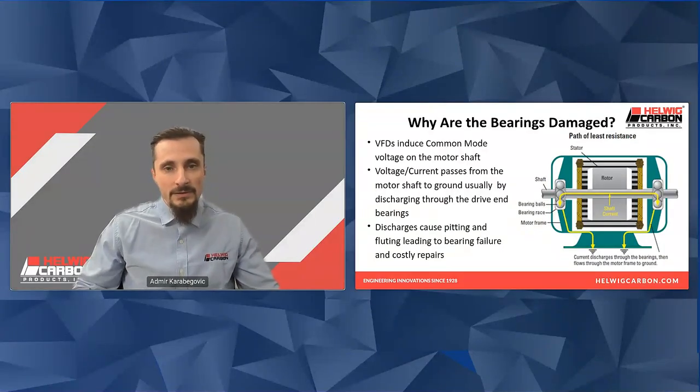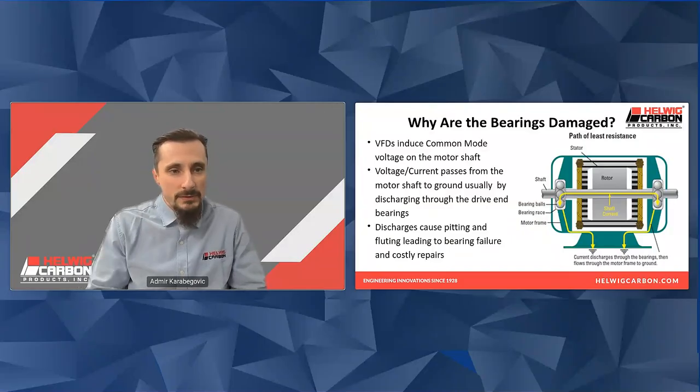So why are the bearings being damaged? As discussed, the VFDs induce this common mode voltage on the motor shaft, as pictured on the right. This voltage and current passes from the motor shaft to ground and usually discharges through the drive-end bearings.